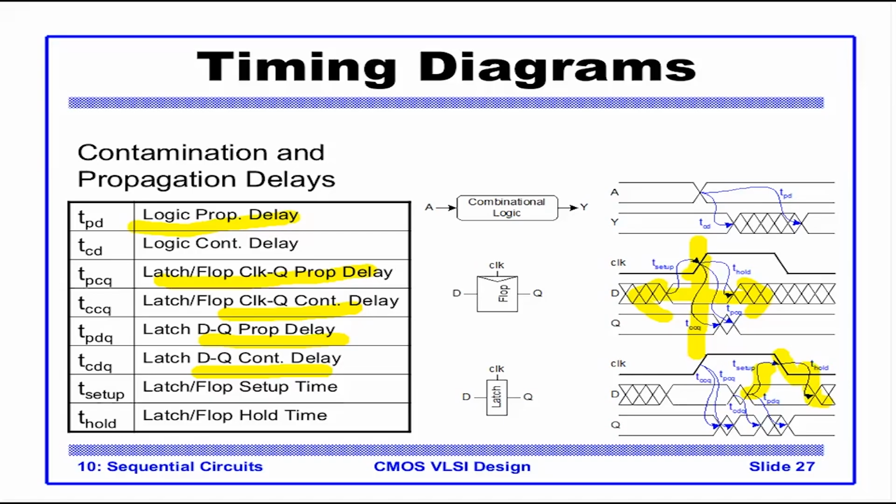A combination logic does not have such a concept. A combination logic is purely a delay concept. Whatever happens on the input appears sometime after on the output. For a sequential element, however, the input should be stable before the trigger edge. For a flip flop, it's always D. For a positive edge triggered flip flop, it is always the clock positive edge. For a level sensitive latch, that is transparent on high, it is always the negative edge.